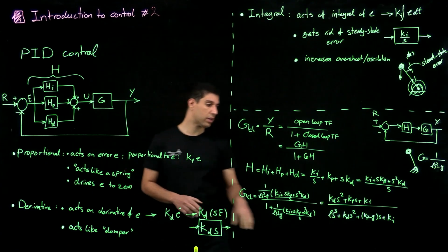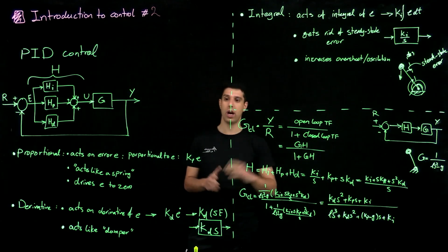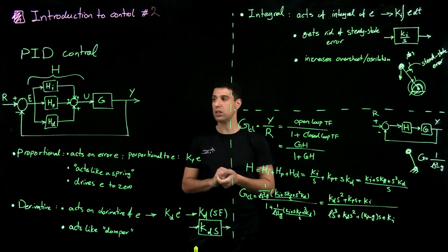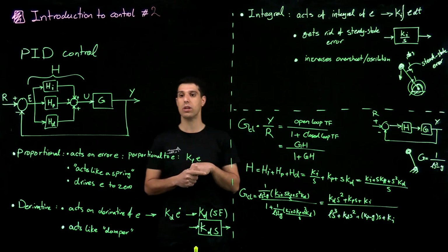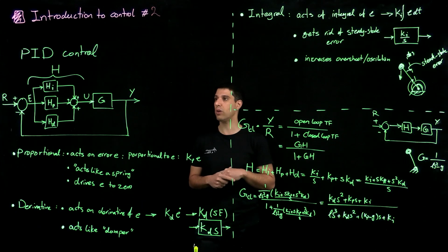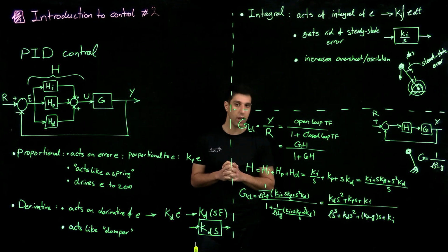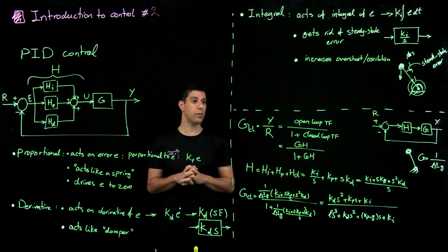Okay, and given the right parameters, Ki, Kp, and Kd, you can move around and shift the position of the poles such that you get the desired behavior. For instance, the speed by which the system rises to the reference value and suppress the amount of overshoot and all of those. Okay, so that's it for the course. So this really wraps up the entire course.